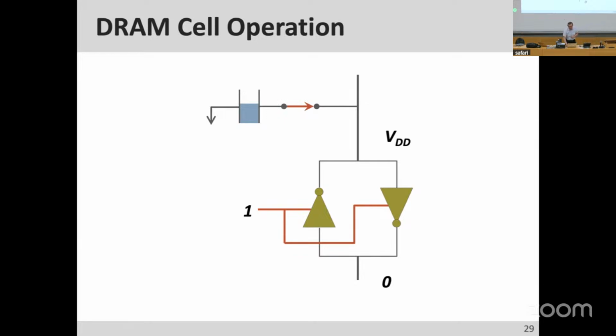Okay, now let's see what we can build on top of it. Once this happens, a very interesting thing happens. Once you amplify the charge over here, this becomes VDD, and the sense amplifier is now strong. This charge goes back, because now the charge is huge over here, and that charge goes back and fills the capacitor. That's how you replenish the capacitor. This is called charge restoration.